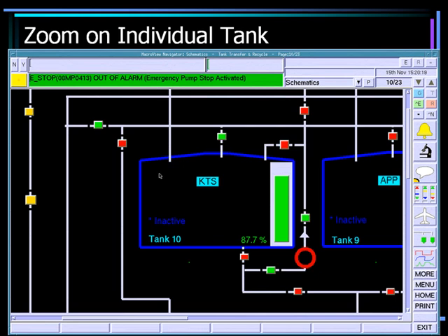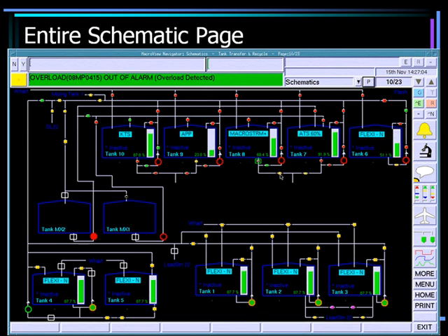If you go back to the big one, there isn't anything in there, is there, Brian? Go back to the other one. Just back one. There's no valve with an outline there. Oh, there is. Yeah. So the green one there, the operator will know that's the valve, and it will also display the valve name underneath the tank. So we're trying to make it so that if the operator is trying to do a transfer and there's a problem, it'll flash one valve, it can't flash all of them, and tell him this valve is the problem. When he fixes that one, it'll go to the next one on the route and say, this one is the problem.